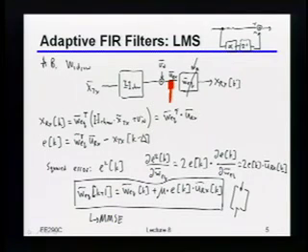So does the delta accommodate only for the time shift in the channel, or does it compensate for the number of taps that are behind? This delta is really compensating for the time shift of the channel. Right, but I guess what I'm trying to get at, and unfortunately this is a slightly bad example, in reality if I was tuning both of these, maybe it would be more clear. If there was an alpha and a beta there, then for the alpha, all of these k's would line up. But for the beta, when I move one down in the vector, that's one bit ago. Then again, when I go to the next sample, one down is one bit ago. Does that make sense?